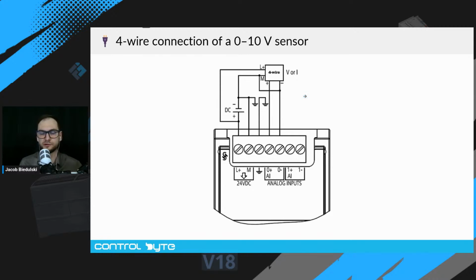You have to be careful because in Siemens documentation, on the Siemens website, you can also find a mix of 3-wire and 4-wire connection. Sometimes the sensors have a separate minus wire, and to have stable measurement, you have to connect this wire also to the DC minus pole, to the M connection of the sensor, okay? So it depends on the scenario, it depends on the application that you use the sensor.